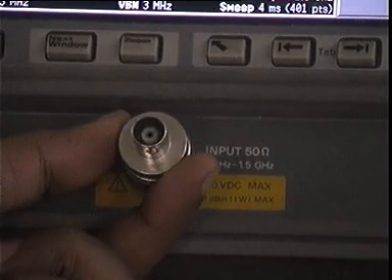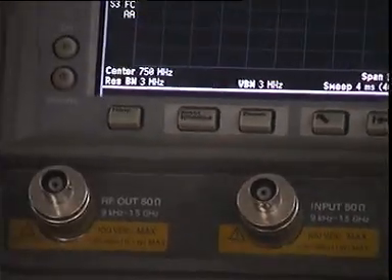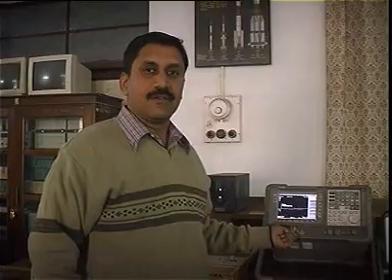What will happen if there is impedance mismatch? Now if you go back to your ES1 concept, all of you have studied something called the maximum power transfer theorem. That is, there has to be a matching between the load and source in order for maximum power to transfer from the source to the load. So in this case, if there is no matching of impedance between the cable and the connector, a large amount of power might reflect back. So what power your instrument is measuring may not be the true power that the cable is carrying, it may be only the transmitted power. So for the reflections to become minimal, it is important for us to have impedance matching.